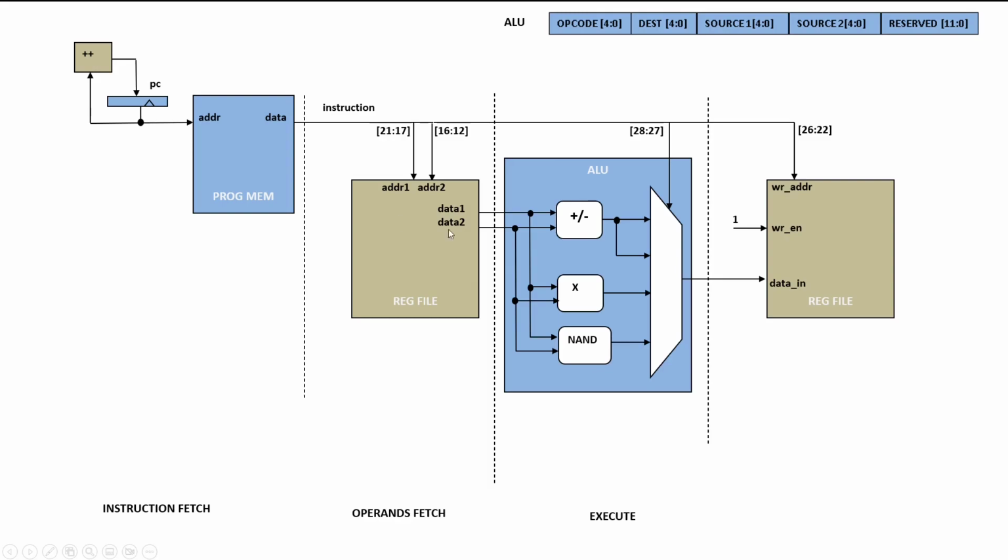So by adding these components, we can support all the ALU instructions. In all ALU instructions, two registers will be read. Then we'll perform all of the operations, but based on opcode, we can select the output of the right operation, and that output will be fed to the reg file. So this is the write back or write results phase of the instruction.